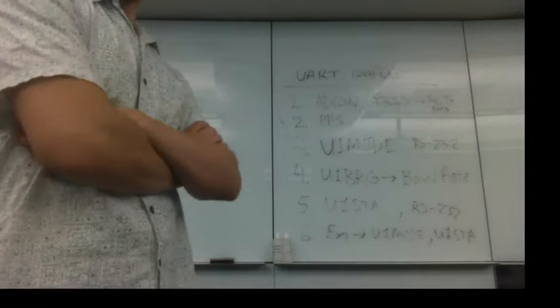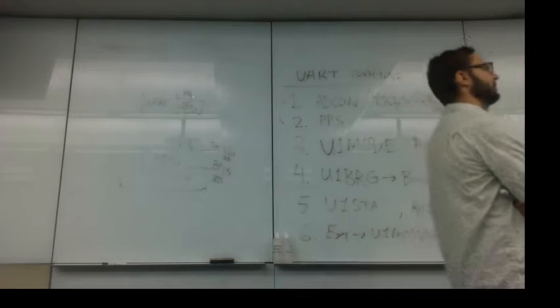So this is what a frame for RS-232 looks like. There's 1 bit that's a start bit. There's 5 to 9 bits for data. There's potentially 1 bit for parity, and then there's 1 to 2 bits for stop. For us, the hardware takes care of all of this. We just put a byte in the transmit register, and it sends it. We don't have to worry about it. But this is what it's doing basically. It's sending a start bit. It's sending 8 bits of data. Sending a stop bit. Then another start bit, and another 8 bits, and then stop. That's what it's doing each way.